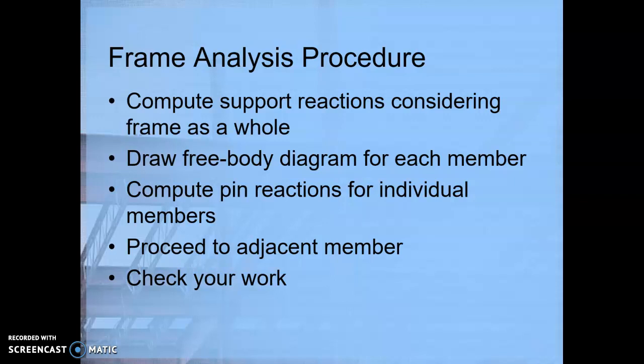So instead, when we analyze a frame, what we are going to be analyzing is the forces that are acting on the frame joints. So the process is going to start off the same as truss analysis. We are going to first look at the external reaction forces, or at the supports. And there may be some missing geometry that we need to find, but once we have the missing geometry and the external support reactions, then we can begin analyzing the frame.